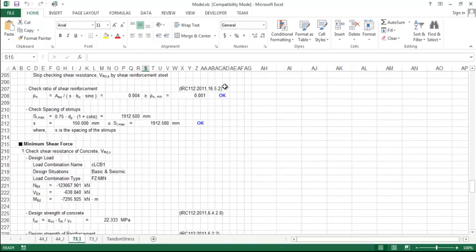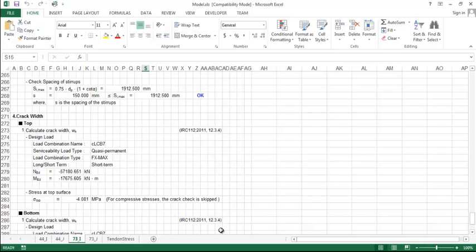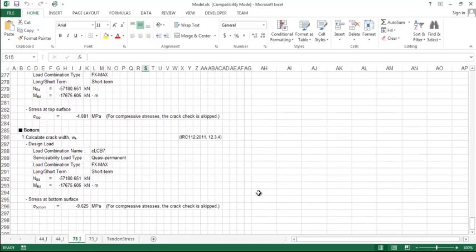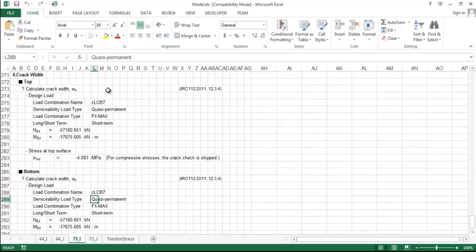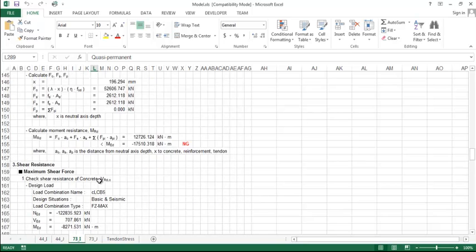Similarly shear checks are done and shear is fine. Even the crack width check is done. Logically, cracked PSC sections are not allowed in IRC, but these are there in certain other international codes, and we do take lots of guidance from other codes at times. So these options have been provided so that in case there is a modification in our code in future, that input could be considered. Moreover, crack analysis is performed and checked, so you could simply redesign these sections so that they are completely under compression. So this is the kind of report that you would get after performing the PSC design.